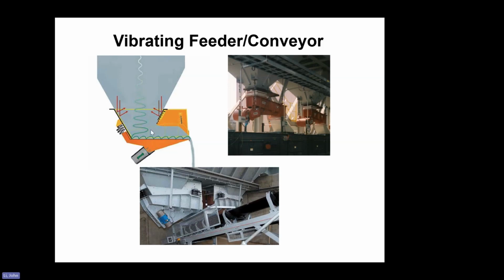So materials vibrate here and discharge here with a small angle here. And usually this opening, the height is critical. If the opening is too big, it will be flooding here. If too small, it will be stuck here, cannot load out, or have some dead materials here. So it's critical to design this vibrating feeder with this opening and angle and height.